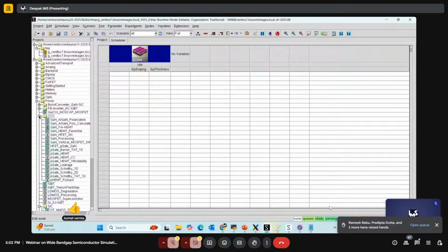First, we have to define the perfect meshing value. Then we can go with the convergence. So this may be an issue in the convergence, and another thing is the physical parameters that we are going to define. Sometimes the physical parameter is not directly accessible in the tool's results, so you have to write it in the command file. Once we are done with the accurate physical parameters, I don't think you will find any convergence issues in any kind of simulation.